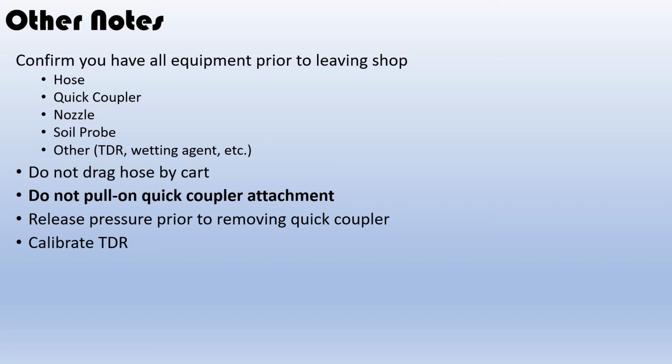Additionally, once you have your hose locked into the quick coupler attachment, any tension on that is going to put a lot of strain on the joints and could cause a geyser and that attachment to blow out of the ground, and that's a big cleanup project. So the irrigation system is under constant pressure at about 115 psi, so any unwanted stress on joints will be